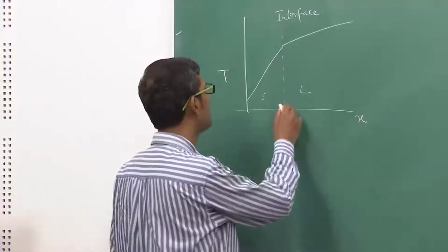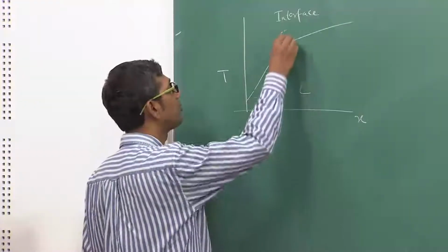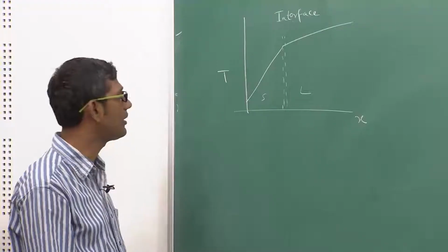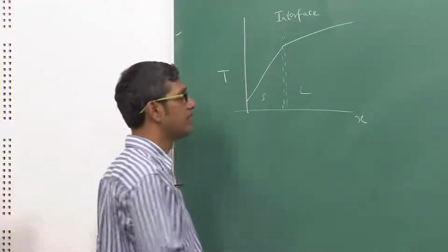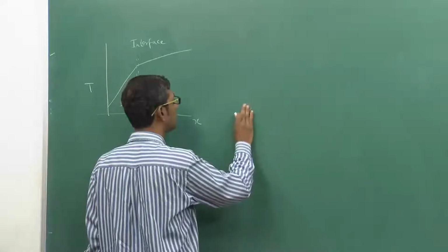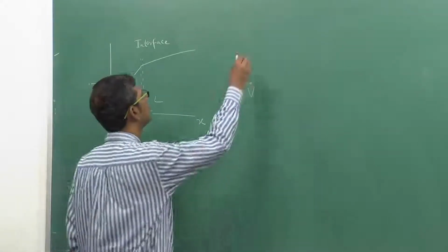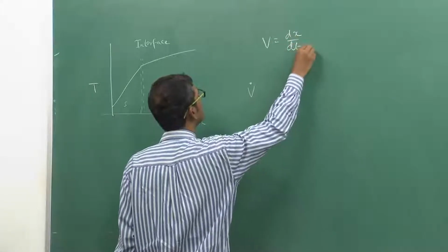So therefore, as the latent heat is getting released at the interface during unit step of solidification, as one layer of liquid solidifies and joins the solid, the amount of heat which is generated will be evolved there. So if I write the growth rate as V dot, meaning dx by dt, because that is the growth rate per unit time.